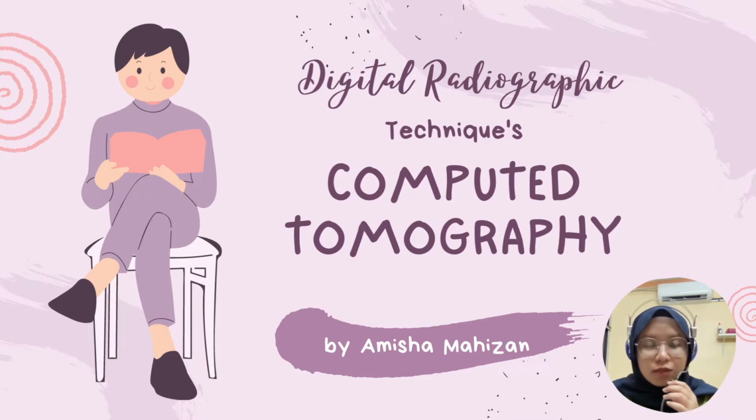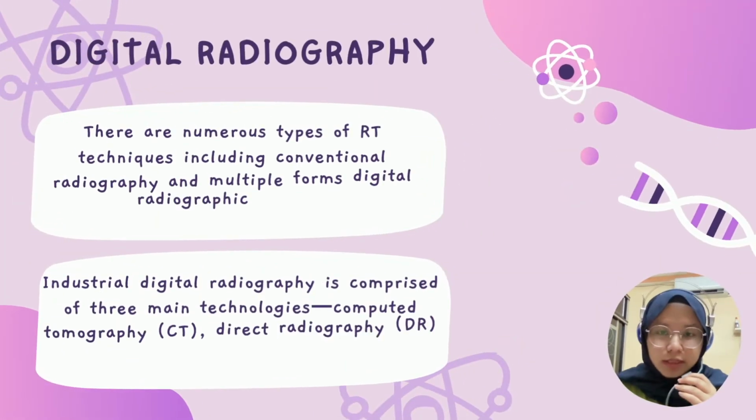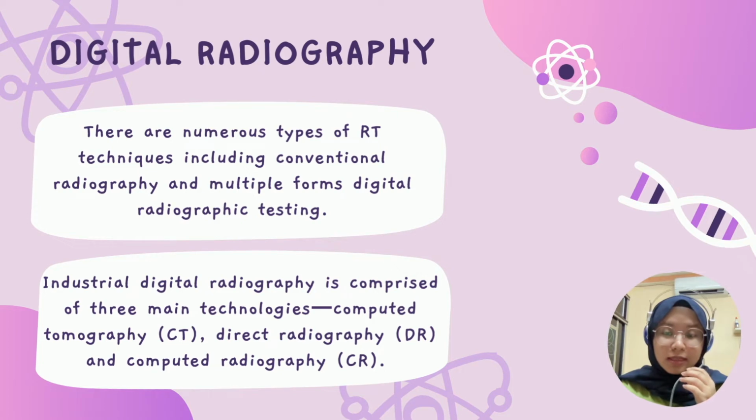Digital radiographic technique, which is focused on computed tomography. Next, moving on. Radiographic testing is a non-destructive examination technique that involves the use of either X-rays or gamma rays to view the internal structure of the component. So RT is often used to inspect machinery such as pressure vessels and valves to detect flaws. RT is also used to inspect weld repairs.